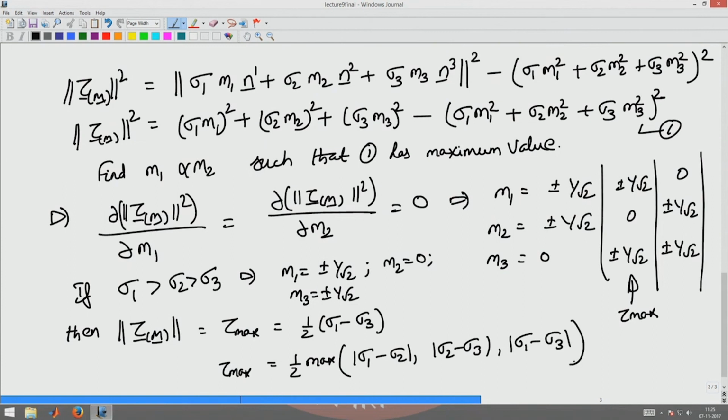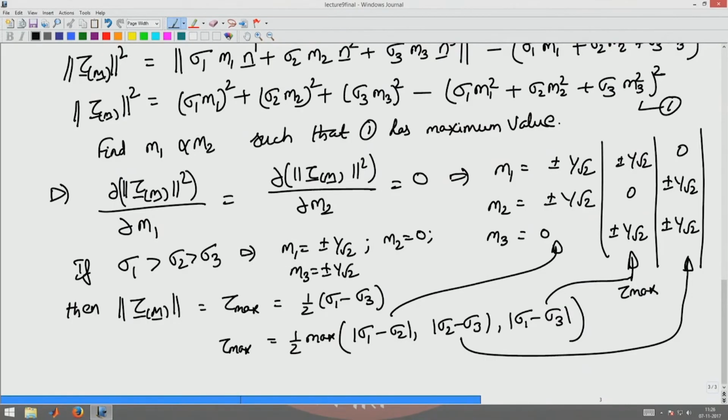Okay. Now, this corresponds to this case in here, sigma 1 minus sigma 3 corresponds to this case in there, and this corresponds to this case in here. Okay. So, depending upon which set you will get one of the solutions here. Okay. I am not going to do the algebra here, you can look up advanced solid mechanics in NPTEL notes for going through the detailed algebra, okay, in the web course. Okay. Now, what is the direction or what is the plane on which this maximum shear stress occurs is the next question we want to answer.